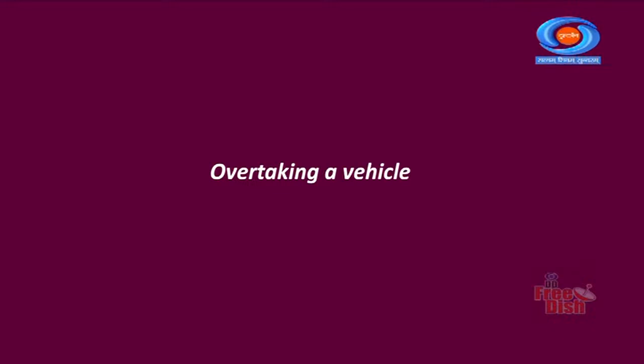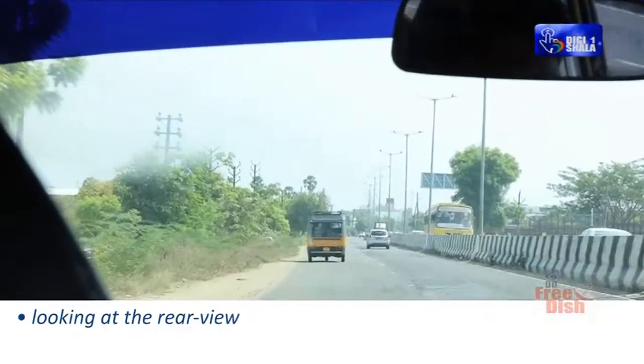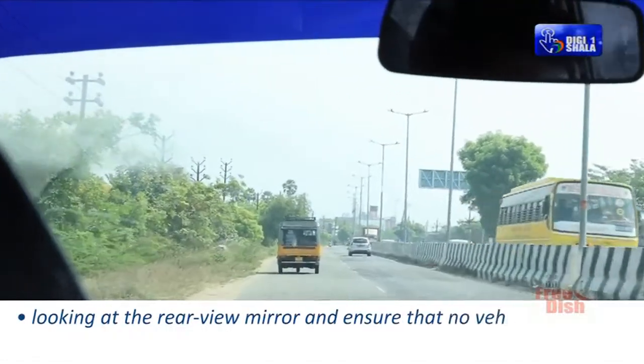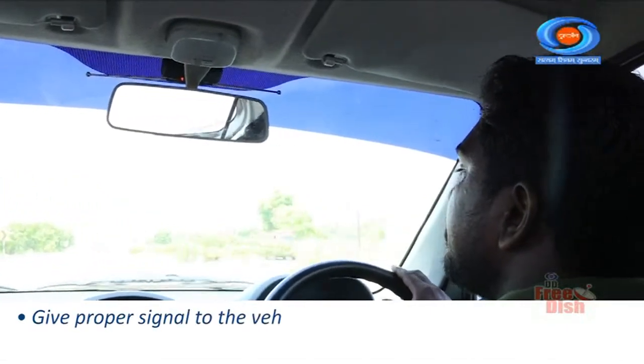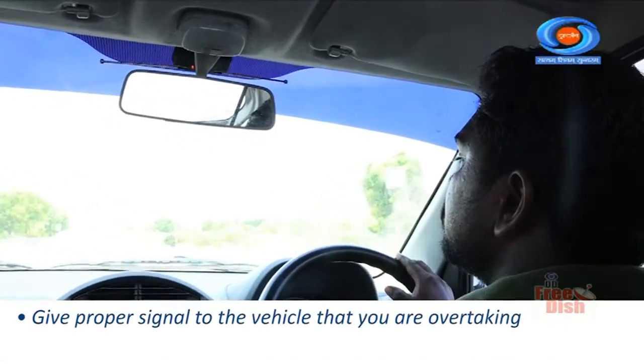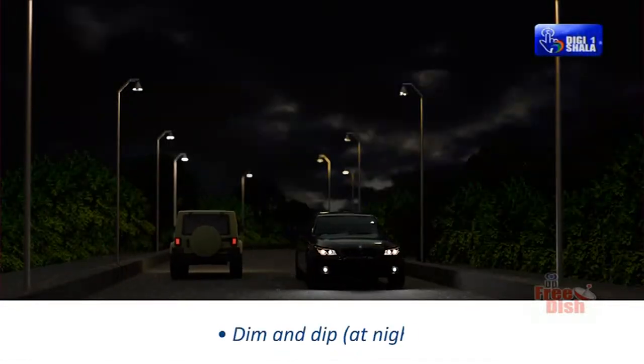Task 1. Overtaking a vehicle. While overtaking a vehicle, look at the rear view mirror and ensure that no vehicle behind you is too close. Give proper signal to the vehicle that you are overtaking. Sound the horn. Dim and dip at night.